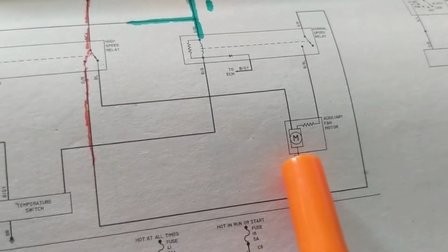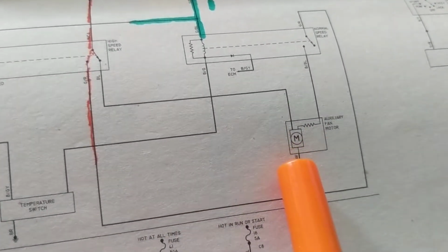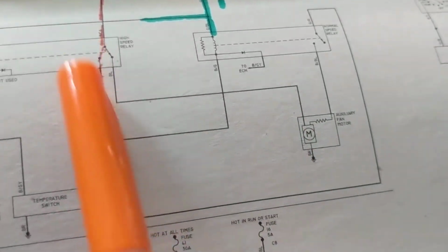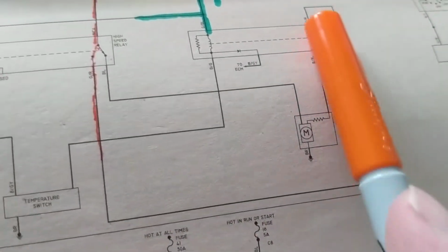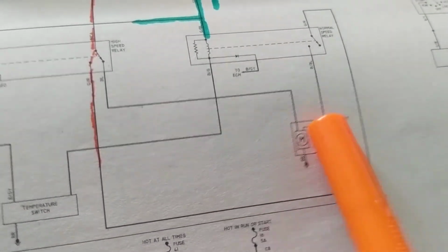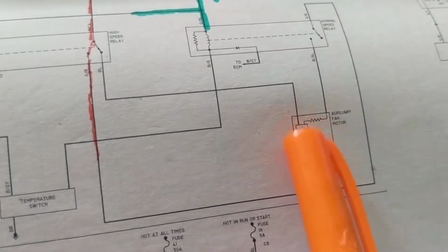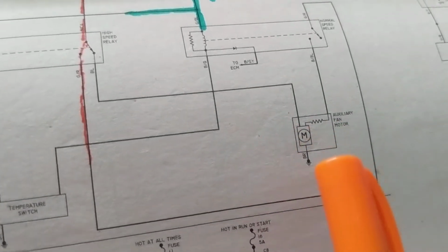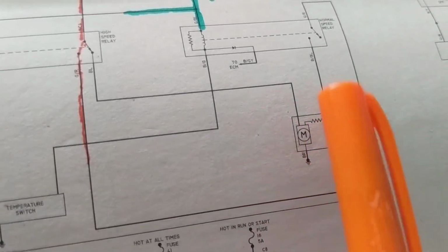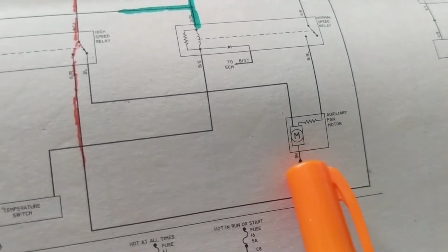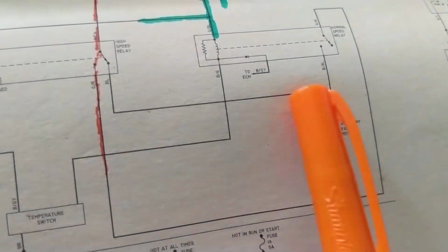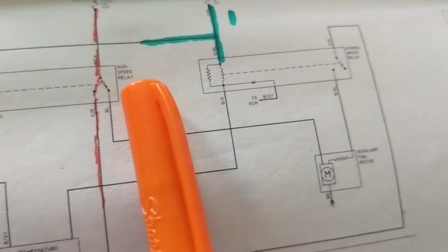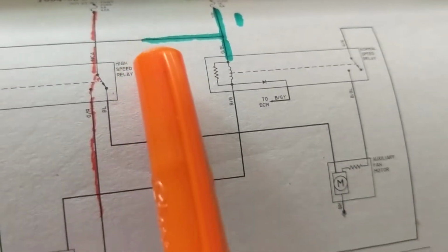In order to activate the motor, two things have to happen. What speed is determined by the resistor in it. When you have a resistor, you have a voltage drop across here. That means less voltage will go here. Less current will go here too, to the motor. Therefore, the motor will decrease its speed. When you do not have a resistor, as you see over here, it will be at full speed or high speed.